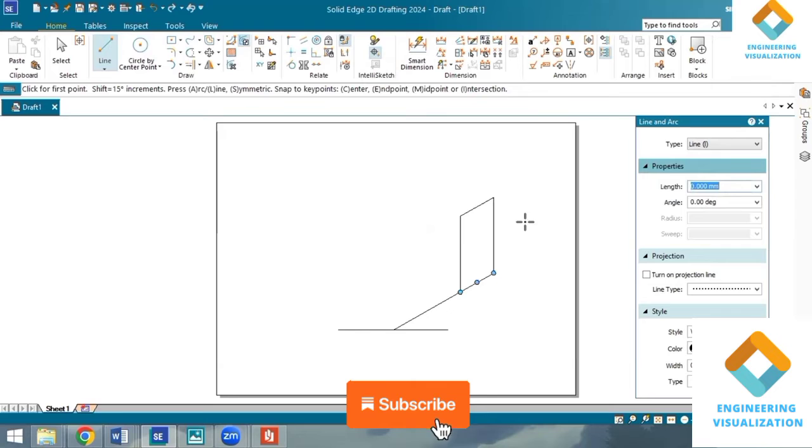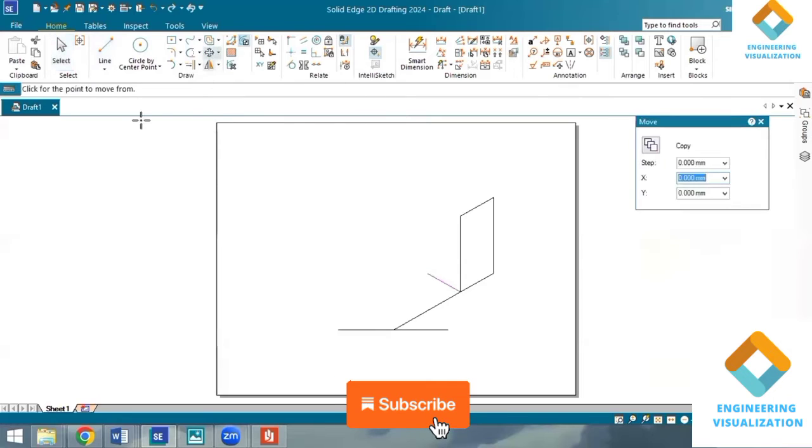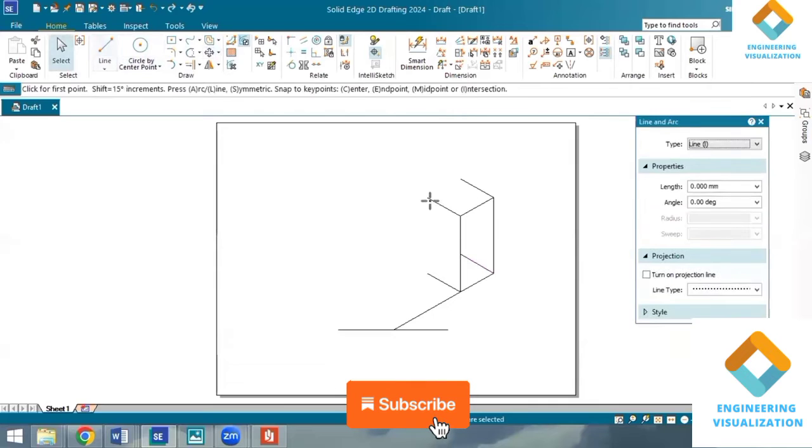Now we have to give the width here, so width of 30 mm at an angle of 150 degree. The same line I'm going to transfer using the move command, create a copy, then place it like this, so it will reduce your effort. Now complete it, so the rectangle block will be over.